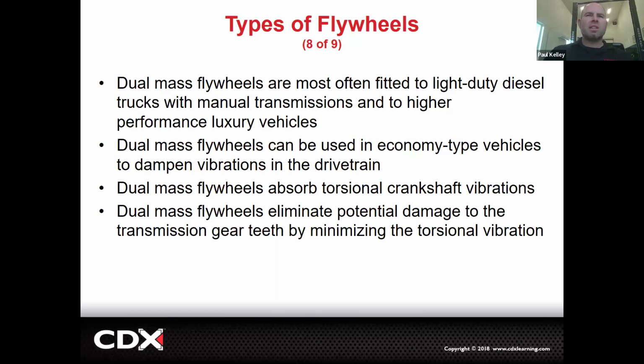However, if it's a Lexus RCF, that's like a performance car, but it's kind of a luxury car. See what I'm saying? So on a RCF, you're going to see a dual mass flywheel if it happens to have a manual. Same with, on a Cadillac, right? If it's a CT4 or CT5V Blackwing and it's a manual, it's gonna have a dual mass flywheel.